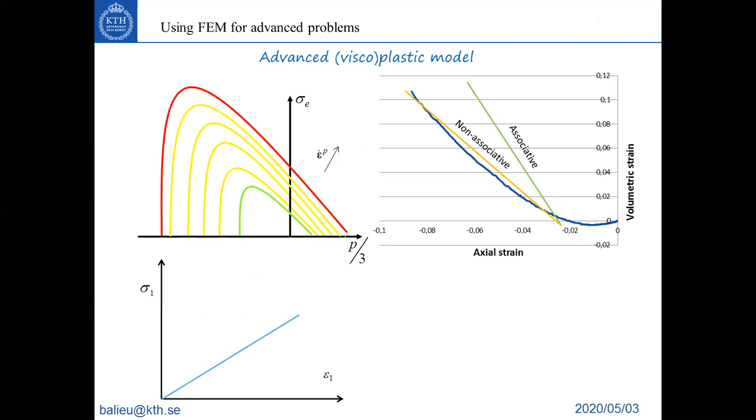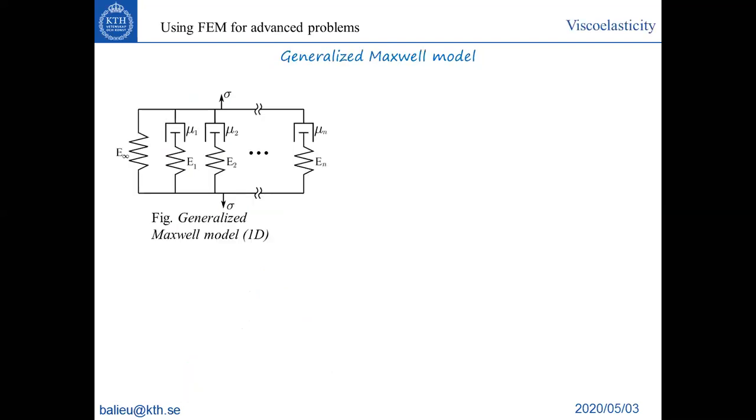Now I also want to discuss what happens before this. The viscoplastic is when you have the yield, and what happens after this yield. But if you have a material which depends on the strain rate, there is a good chance that this material also depends on it before the yield. So when the material is still elastic, if it is dependent on the strain rate, the material is viscoelastic. I presented the viscoelasticity to you last week.